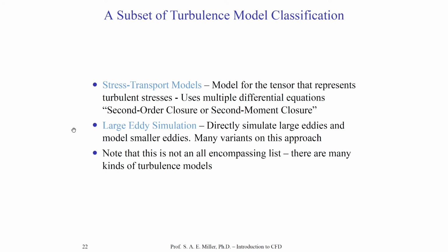The bottom line, if you're a user of CFD, is that you have to choose the correct turbulence model for the right job. And you have to know something about the flow in advance, much like the composite profile of a turbulent boundary layer, to set the number of grid points and even choose a particular turbulence model to model that type of turbulent boundary layer. It becomes very complicated, and you can spend a lot of time just on these subjects. In fact, typically in graduate school, there's a whole class on inhomogeneous turbulence and its modeling.